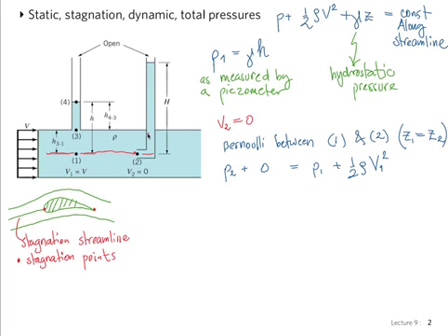What we have here is the same situation, an obstacle. The obstacle is this little tube. The back of this tube is a flat wall. The fluid runs straight to that wall and must stop, because all the liquid inside this tube is static. It's not moving, it's not flowing out here. It becomes static. However, the height of that column is higher than if it was just the static pressure, because of the effect of that pushing of the fluid that has come to a complete stop here.